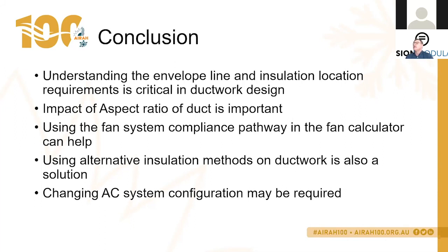What insulation R value is required for the preconditioned air ductwork in conditioned space? Not sure how to answer that question because it depends on the design of your system and what duct you're using, where in the application, whether you're talking exhaust duct, return air duct, or supply duct. Supply duct has to meet the R value requirements.